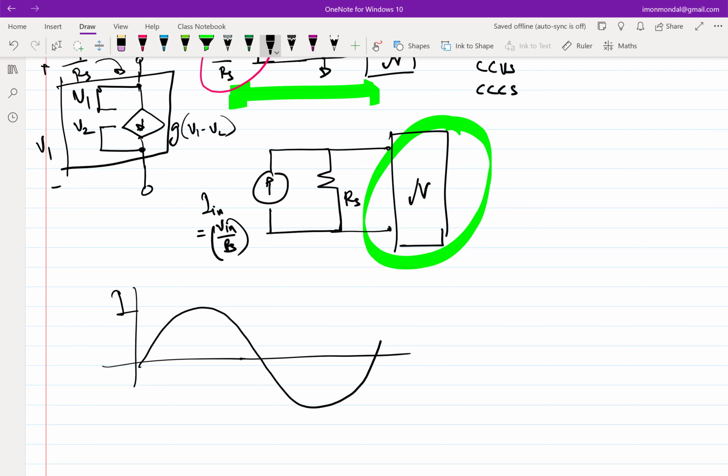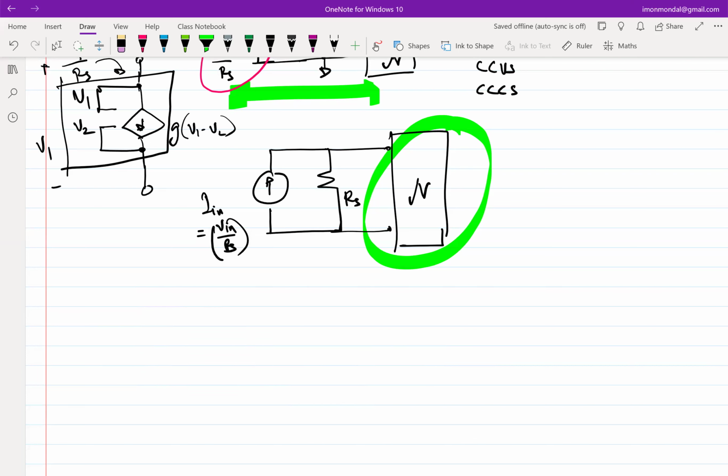So now if you have to deal with actual nonlinear elements, then you have to develop a framework, just like we have a framework of dealing with linear elements, right? We have done multiple courses of linear analysis. So we should also have some framework of dealing with nonlinear elements, because ultimately, the bedrock of dealing with linear elements is superposition. We start off assuming that superposition holds, then we go ahead and prove multiple theorems. But we don't have such luxury while dealing with nonlinear elements.